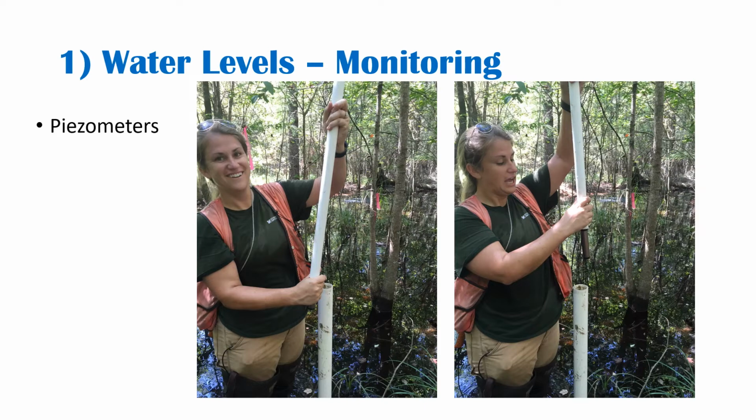These are electronic devices sitting in water, or wildlife can come knock them over, a tree can fall on them, anything. And actually here I am checking another set, and what happened here was that we had the device hooked up with wire that was rusting, and eventually it broke. And so what I was trying to do was retrieve this transducer because it had valuable data that we needed. And after this, we replaced all of our wells to have stainless steel type clamps that would not rust over time.